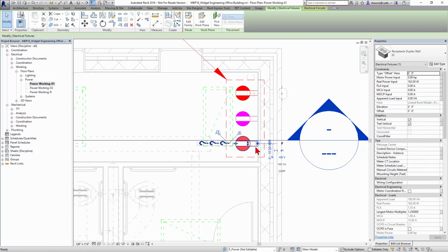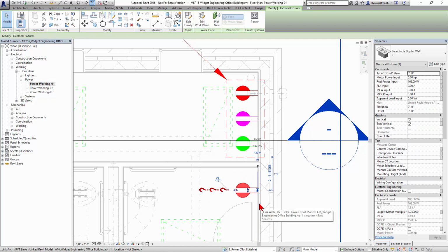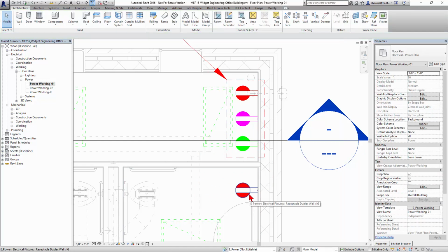Now, with end users in Revit, a lot of times what I'll see is people will copy something. They'll copy an outlet someplace in the model or take one and make a new one based on it, and they don't necessarily realize that that new outlet did not add to the circuit of the original outlet. You see, Revit's not AutoCAD, right? It's not going to copy all of the parameter values necessarily. Well, it's going to copy the properties and the parameter values, but that attribute or that setting that says I was a part of such and such a panel, Revit doesn't know that yet.